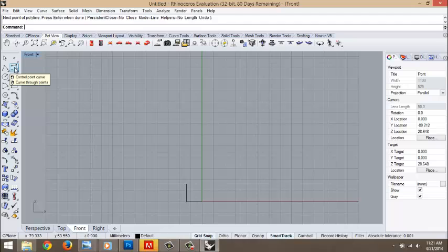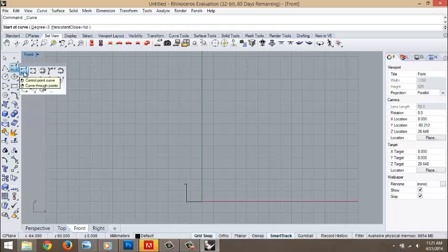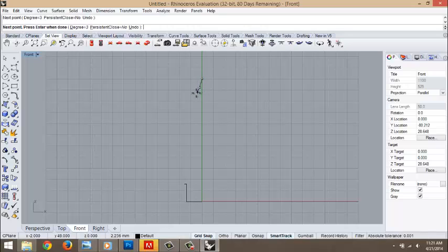I need to go over here and select the kind of line I want. We want a curved line. So I'm going to click curve here, and little box. We either can use the control point curve or the interpolated curve. Let's try the control point curve here. Now that's 10 boxes, so this is 9. It's my starting point. Now I can't go beyond the point down here width-wise, so I'm going to start here and just begin to draw a few curves to help make my rocket nose cone the way that I want it.